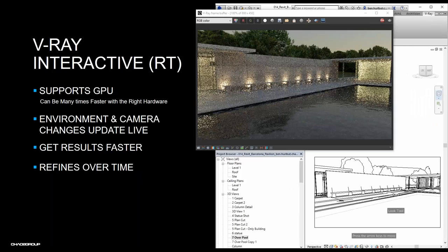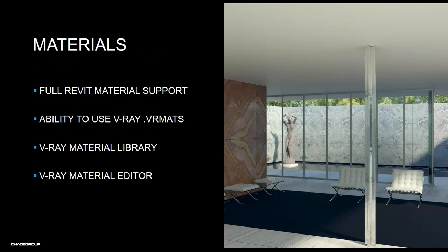On the other hand, you can use the other mode, RT, when you set up the scene, when you set the camera, when you set the materials, the light conditions, everything. It supports CPU or GPU. And without any altering, V-Ray will render everything.